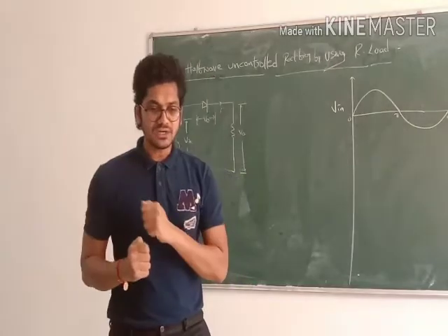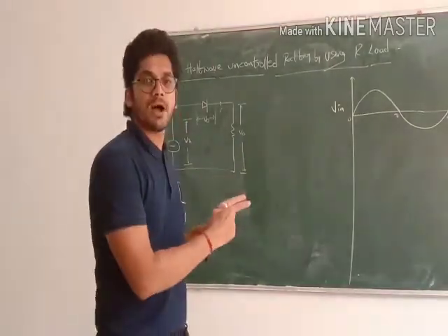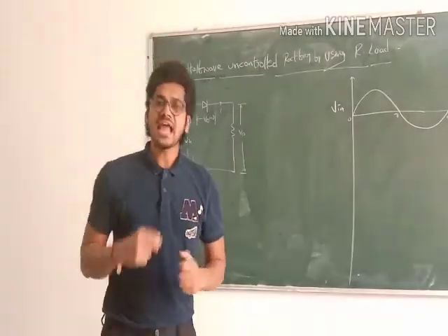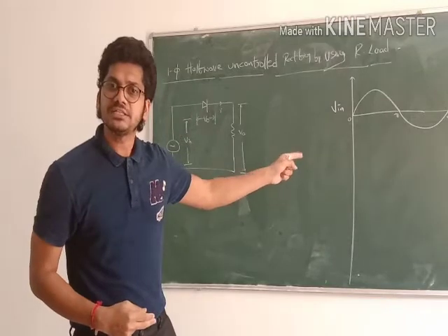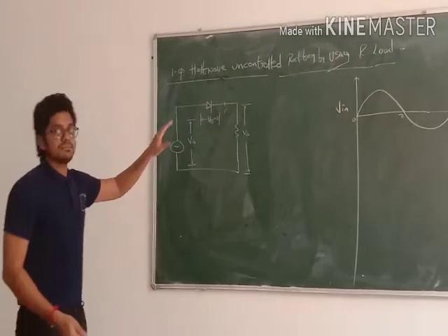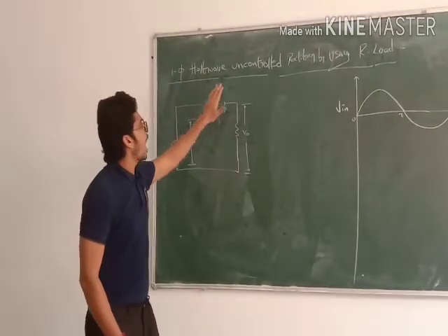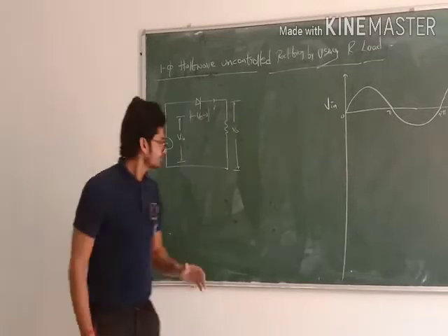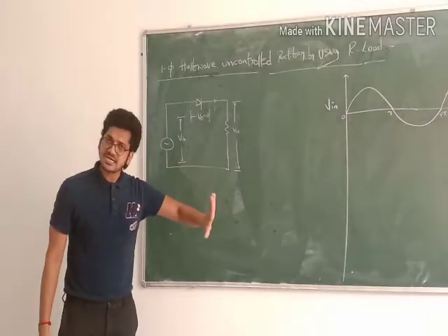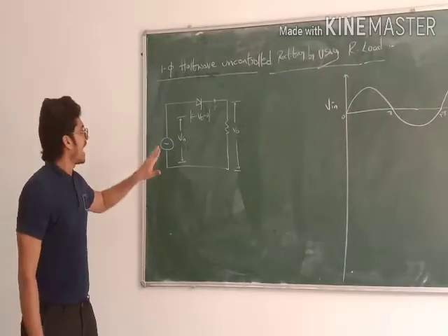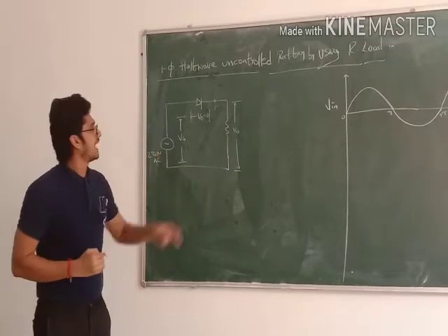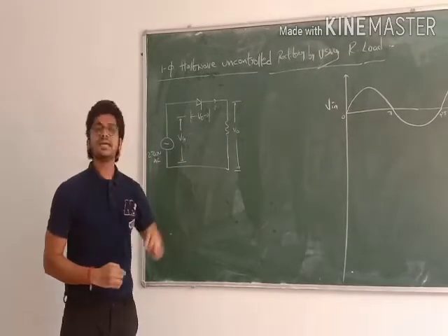Friends, the main advantage of this video is that it is not only the theoretical part, I am also going to explain the software part. By using MATLAB, I can verify whether the theoretical aspects I am giving are right or wrong. Please follow the circuit diagram; I have given its name as single phase half wave uncontrolled rectifier with R load. Obviously, the input is my AC supply and the output is a DC supply. For that purpose, I have taken a 230 volts AC supply as my input, a diode, and a resistor.